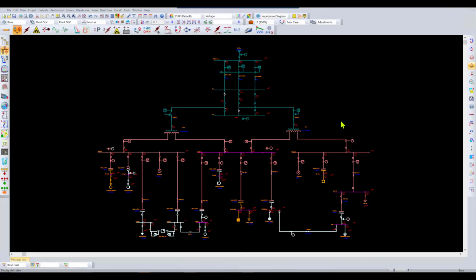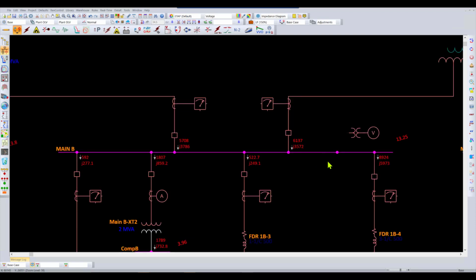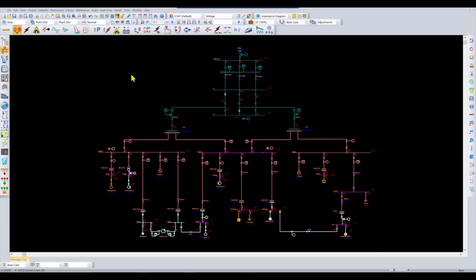Let's take one more example of an industrial system where we essentially have a power grid. We have a couple of industrial motors in the system. We have 2 different generators here, and a number of other miscellaneous auxiliary loads in the network. Now in this case, we'll take a look at what happens when we are trying to use OPF to just improve our voltage only. And here we can see that in certain parts of the system, with the magenta color, you can already see that there are certain buses that are under voltage in the network, and we want to have a bit more of a flatter voltage profile in the electrical circuit.